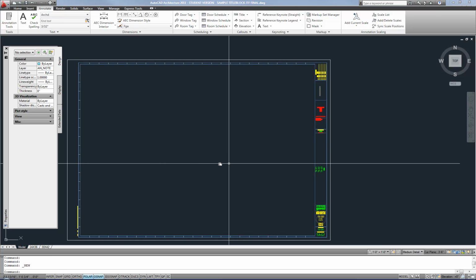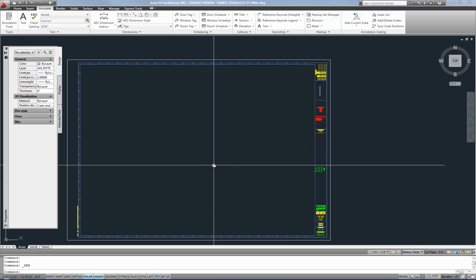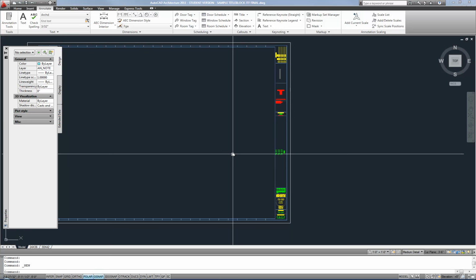So here's an example of a title block and how attributes are very useful in setting it up. Because when you bring the title block in to your paper space, you want it to be a block, but you would often need to update things like this project name, things like that. Keep in mind, when I recorded the XREF video, I pointed out how title blocks are often used as an external reference.